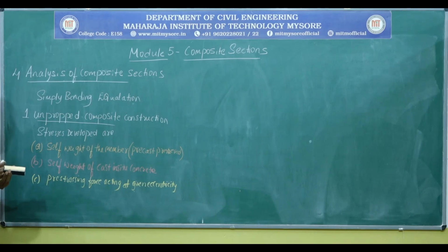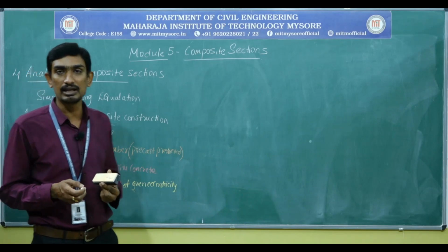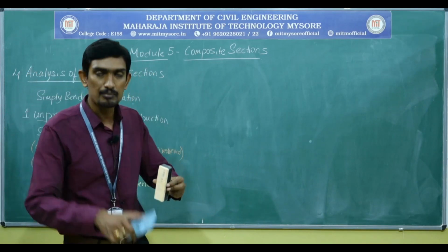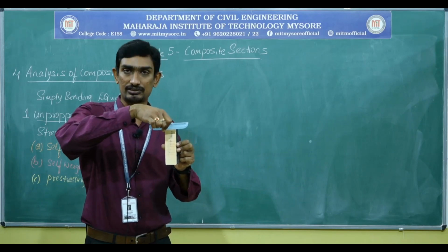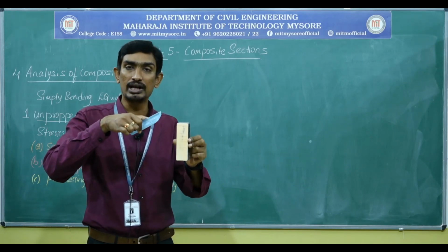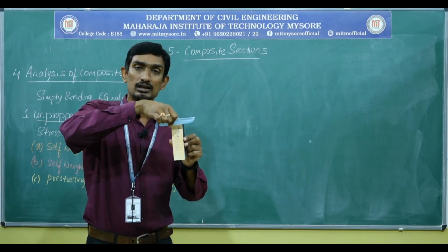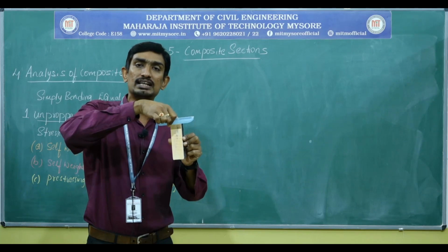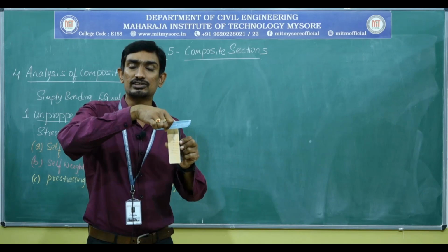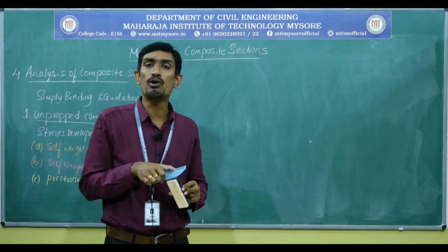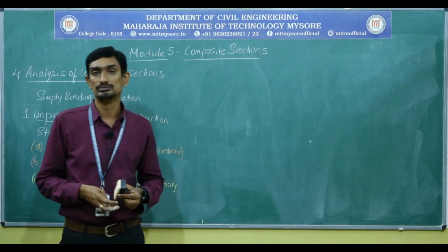Now come to the very interesting thing. After hardening, that means once I combine these composite section elements, that is the precast pre-stressed unit and the cast in situ slab, and once the composite section hardens after casting, then this composite section will be subjected to the live load.